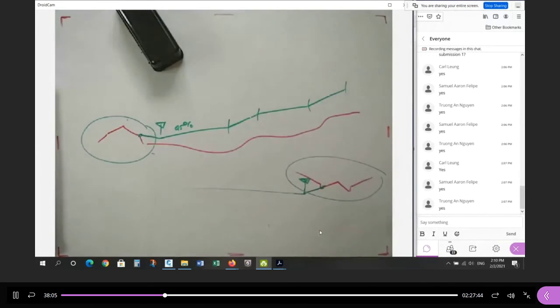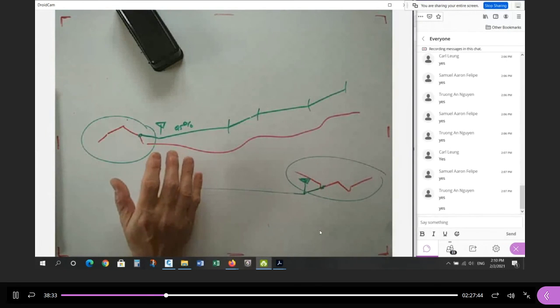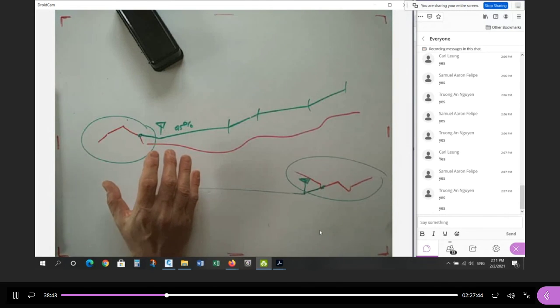Does everybody understand what I'm trying to do and why it's a problem? So the original topo is pre-construction of Ledger Way, so now I don't know what Ledger Way looks like. I need to model it, right? Now, the proposed model might not be exactly as it was constructed. You remember when they construct it, there's a little bit of tolerance. It'll be off a little bit, might be a little higher, a little lower, but it'll be very close. So what I propose we do is model the proposed and just pretend that it's existing, knowing that when it was built and approved after construction, it was within the tolerance.